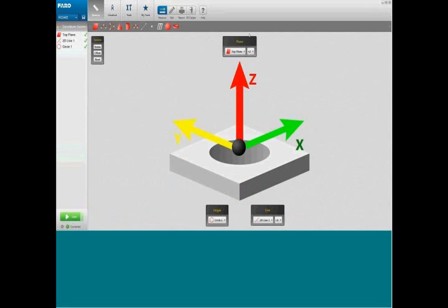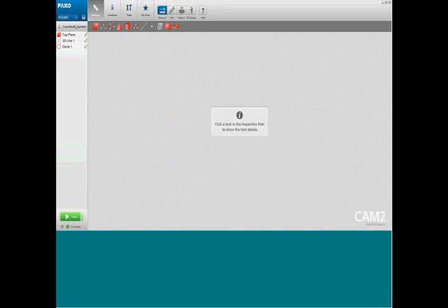So here we can choose the plane, for example, the top plane. We can then choose the direction of the axis that comes from that plane. We can then choose the line at the bottom. And again, we can choose the axis. And we can choose the origin, in this case, circle 1. We can also rotate and offset the coordinate system via the options menu here. If we press the reset button, this deletes the coordinate system. To return to the image, we just click the coordinate system at the top.